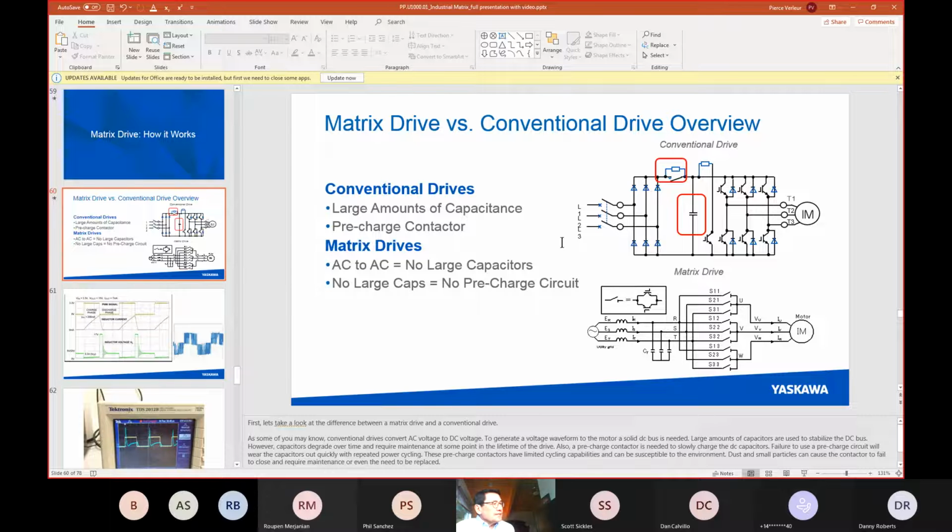So here's the AC line. We've already said we can't really see it, therefore we can't control anything from that. We make it into a DC bus, which is a constant voltage. And then we use this 6-transistor H bridge to pulse this voltage out to the motor, controlling voltage to create a desired current. But we only have one level of voltage to control, and therefore the only thing we can do is control the time on and time off that we apply that voltage to the motor.